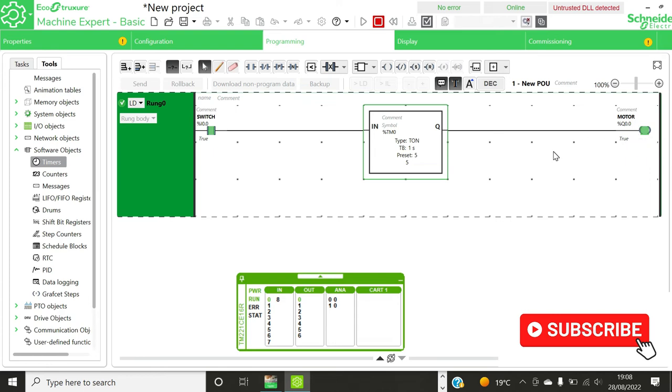The other type of timer, the off delay timer, is actually the opposite of the on delay timer. It works in a way that when you switch off, the motor will remain running for the specified amount of time. So in short, that timer gives an output for a period of time even after the input has been withdrawn. We can click on the same timer, we change its type to T off and see how it works. We can then say apply.